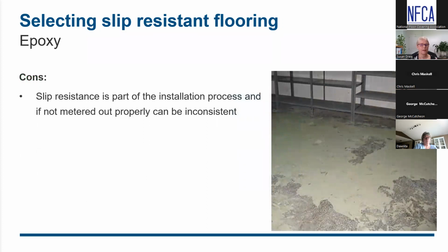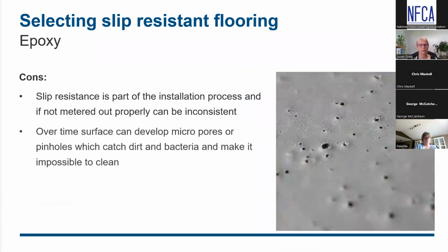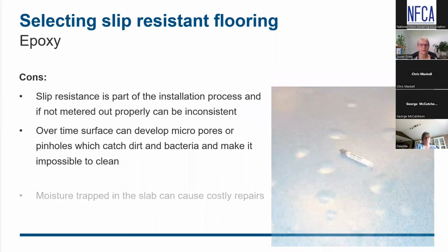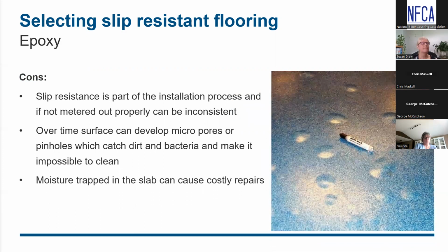The cons with epoxy is that slip resistance is part of the installation process, and if not metered out properly, can be very inconsistent. Over time, surfaces can develop micropores or pinholes, which catch dirt and bacteria and make it impossible to clean that floor. So the challenge is on the installer to get it right. It's all on the installer. Yeah.